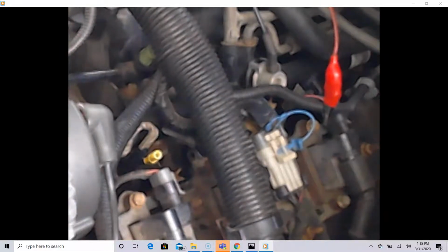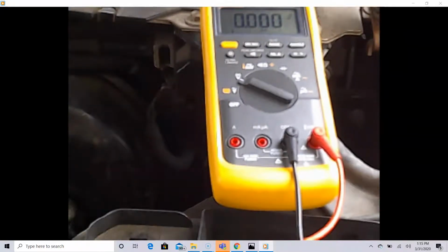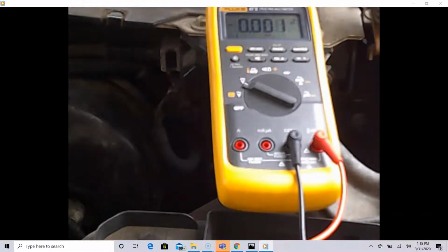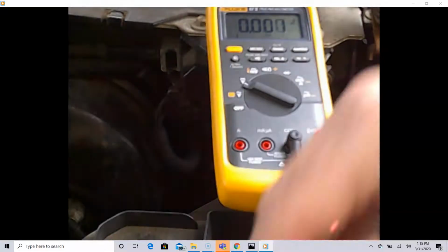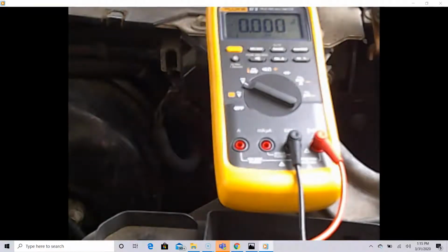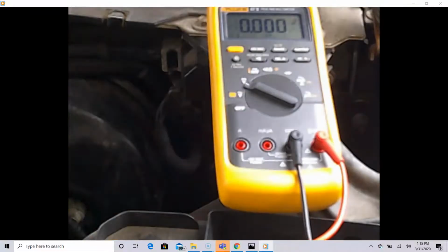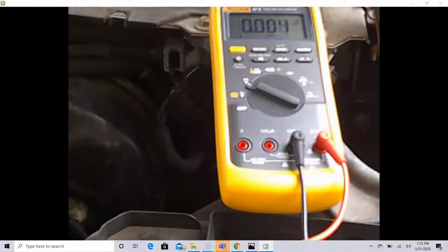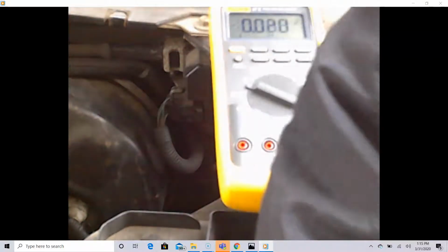I do have battery power there. What we are going to do now is connect that meter between the battery, 12 volts, and that connector. And that will show us the difference between the two. Again, if we do negative, it doesn't matter. Same thing. All right, so I'm going to start by taking the red lead from the meter and connecting it to 12 volts.